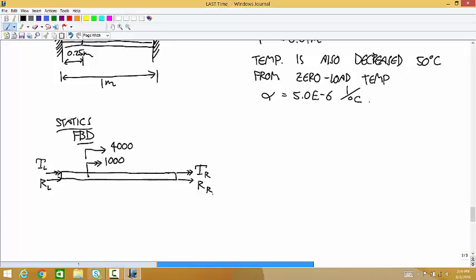Anybody unclear why that, like why doesn't the temperature go in there? On the free body diagram? Yeah. Because that changes after we... Yeah, right. So we apply that as a constraint afterwards, and the temperature decrease in a way really does show up here. It's just going to affect those values of the reactions. So all that's already included in what we have.